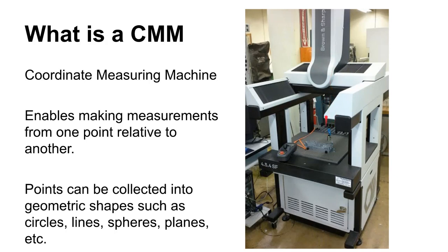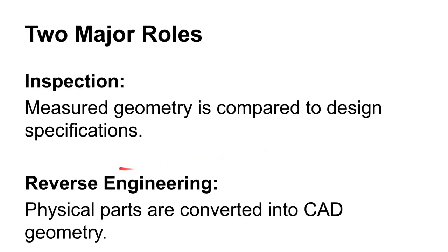And what you do on this thing is you drive a little tool around, and when that tool bumps up next to a part, you get a measurement. And so you can get measurements all over a workpiece, and you can get measurements on opposing sides. You can get things like a distance or features of size, things like that.